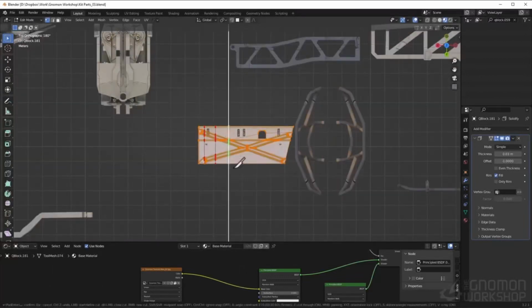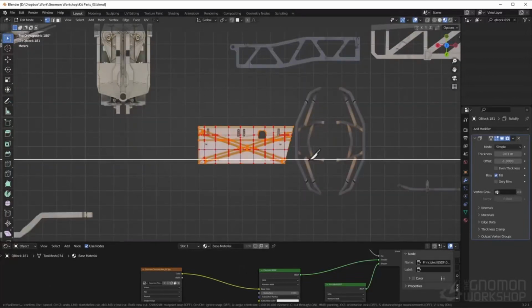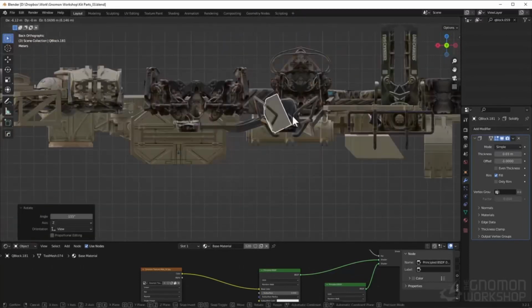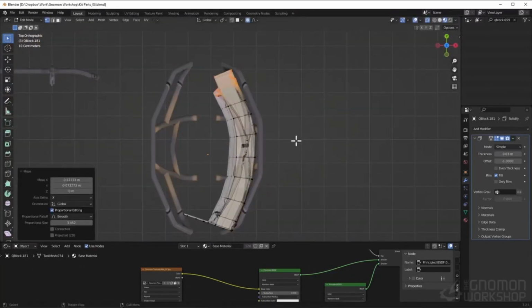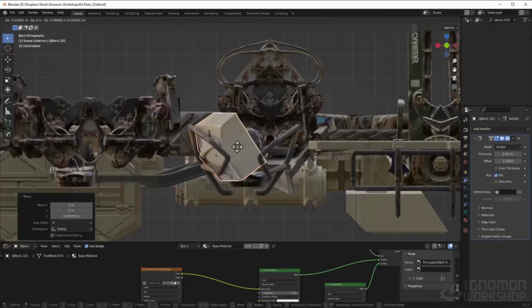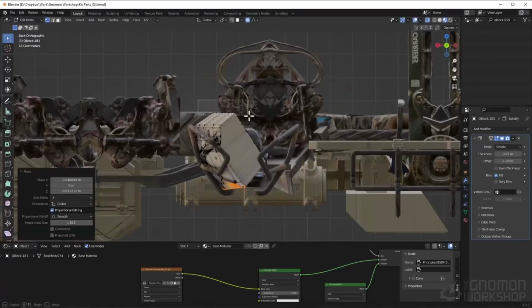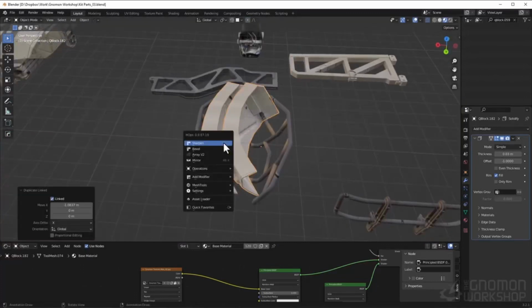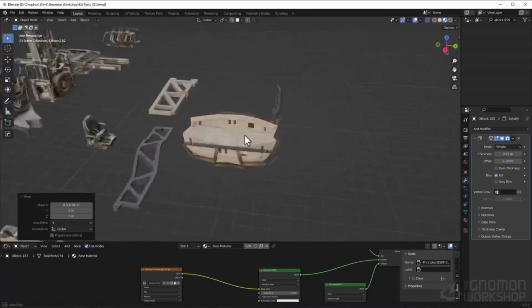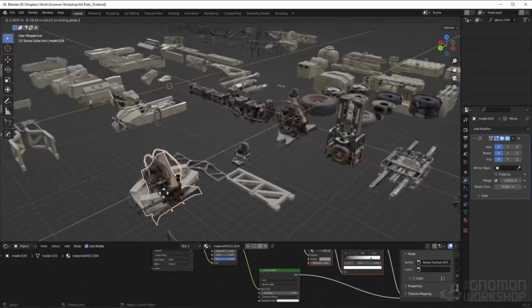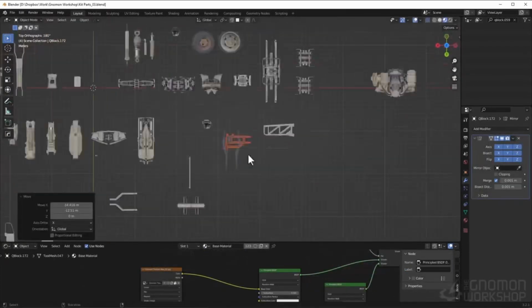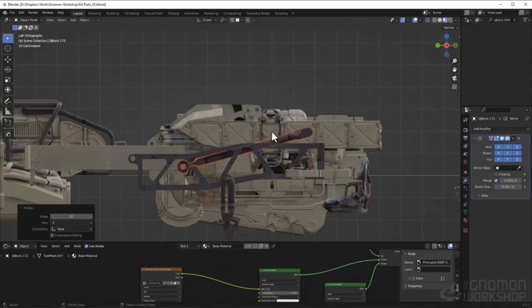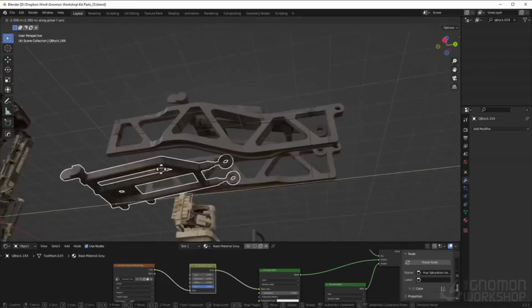Here I'm cutting subdivisions into the shapes so that I can use proportional editing to mould it into the shape that I want. This is a really easy thing to do. I'm using the knife tool in edit mode and I'm making sure to press A for angle constraint to get the parallel lines and C for cut through so the cuts affect the back facing polygons as well. And as you can see, it's really easy to use proportional editing to go in and mould the part to the shape you want. Now I've got some cool blocks of shapes that I think will be useful, I want to start adding some more internal structure type shapes.